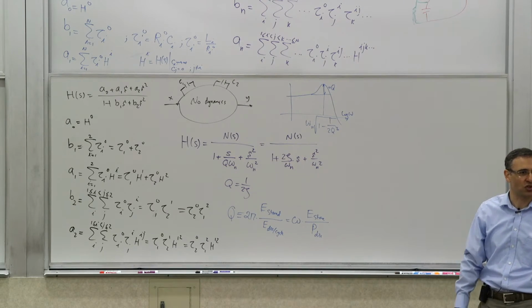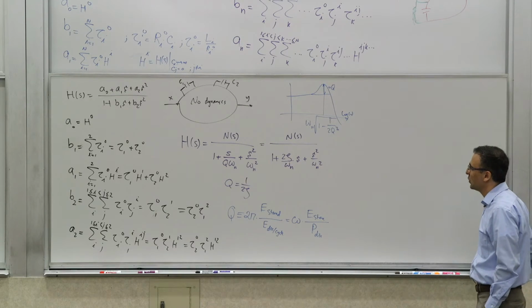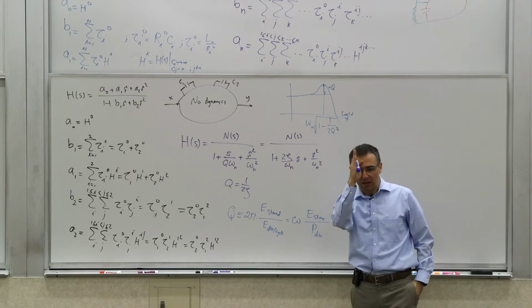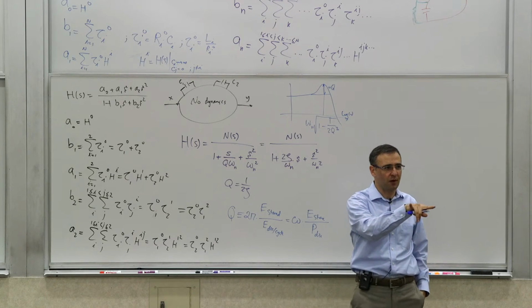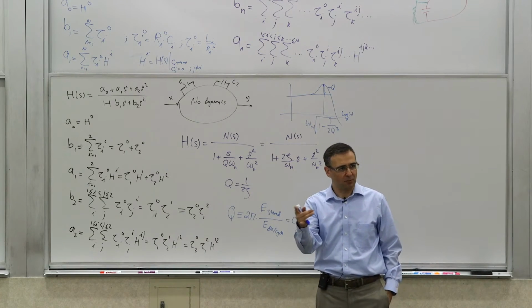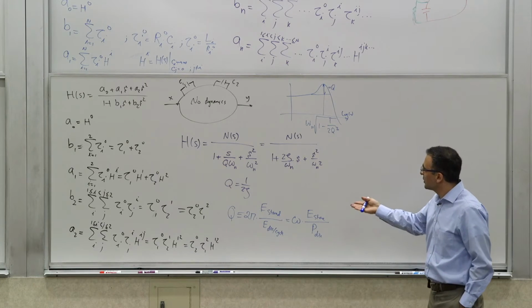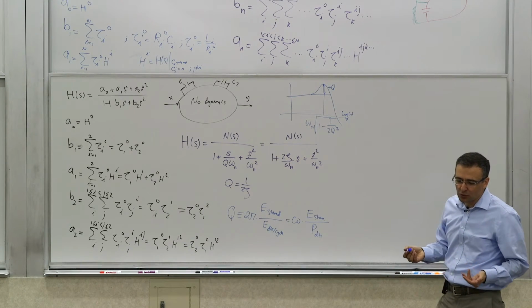That's the point where switching happens, and you can see it's the Q of 1/2. So that's the point where it switches from real poles to complex poles. But anyway, that's good. So that's Q, and then omega n are the two things we want to calculate.